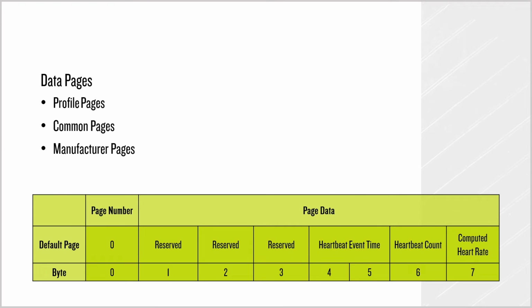8 bytes of application data can be encoded each time a message is transmitted over an ANT channel. ANT+ device profiles specify encodings for this data. In ANT+, the first byte of each data message is always the page number. The encoding for the remaining 7 bytes changes depending on the page number. Together, we get what is referred to in ANT+ as a page. There are 256 available pages in most profiles. Available data pages are broken up into 3 primary regions.